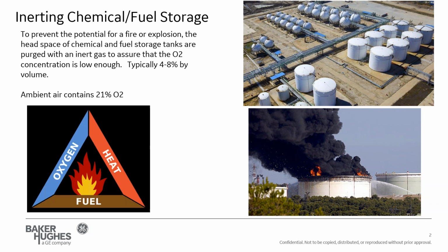So there are two ways to monitor a tank. You can do it by pressure, or you can do it by oxygen measurement. With pressure, it's a good measurement, but it doesn't measure the oxygen content. So what's typically done is you measure the oxygen content of the headspace, and you have a feedback control to limit the oxygen to the 4 to 8% value.